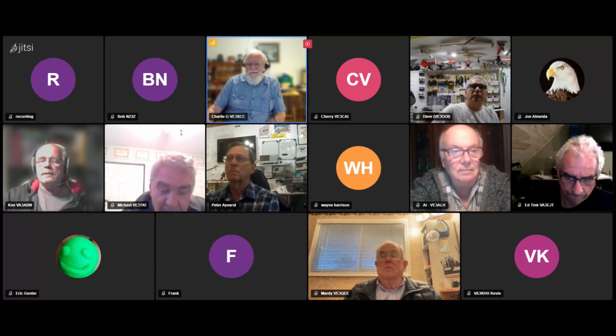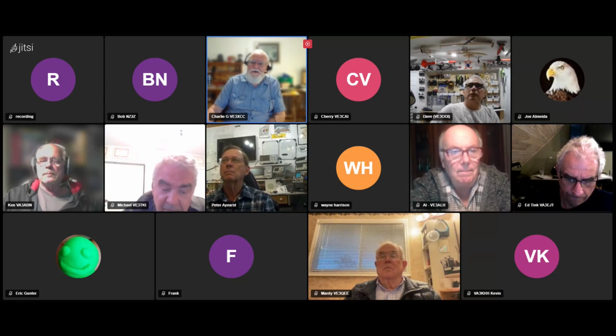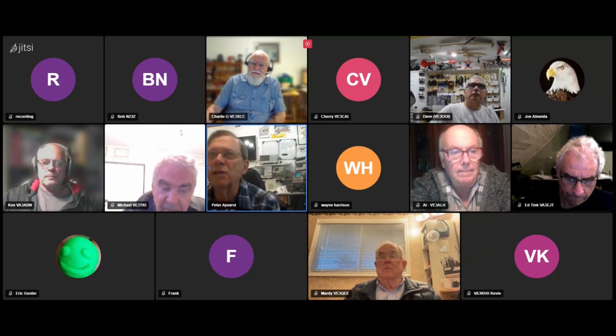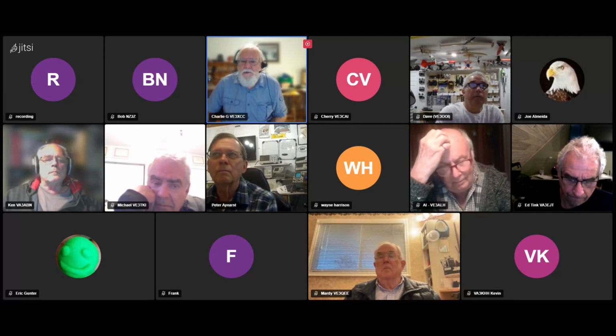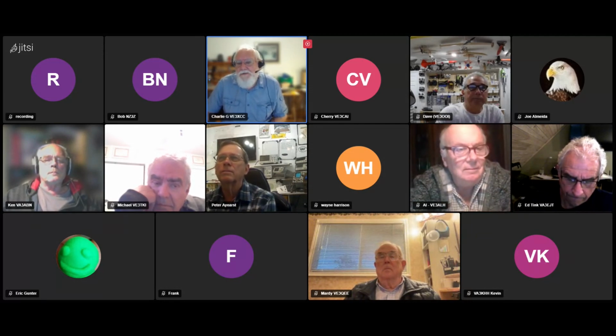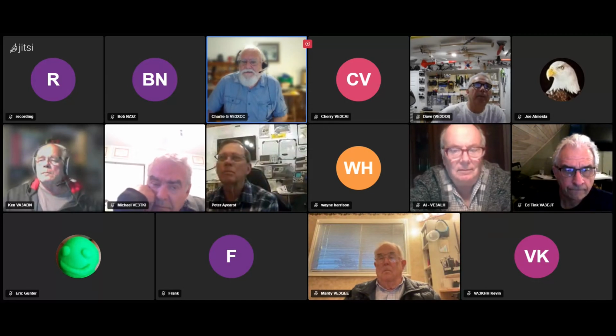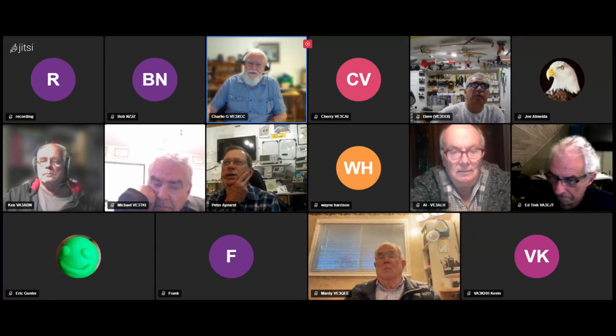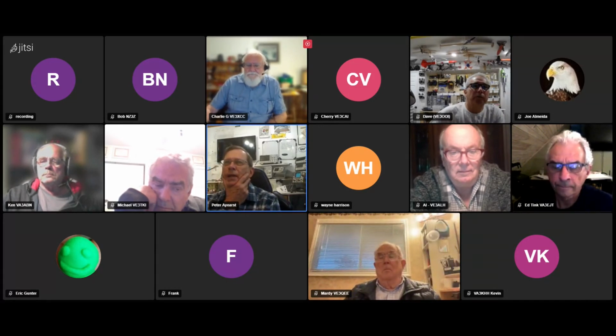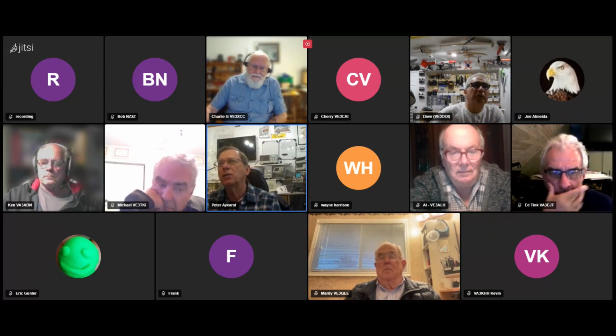Just last call, Peter, this really has to be done on something like a bandpass filter. You've got a low pass that you're trying to measure this on, and I'm not sure how you can do bandwidth on something like that unless you start off at DC, not at the 2 meg you're talking about. In this case, the number worked because I'm spanning from 1 to 30 megahertz, so the peak is at 1 megahertz, and so it calculates out great.